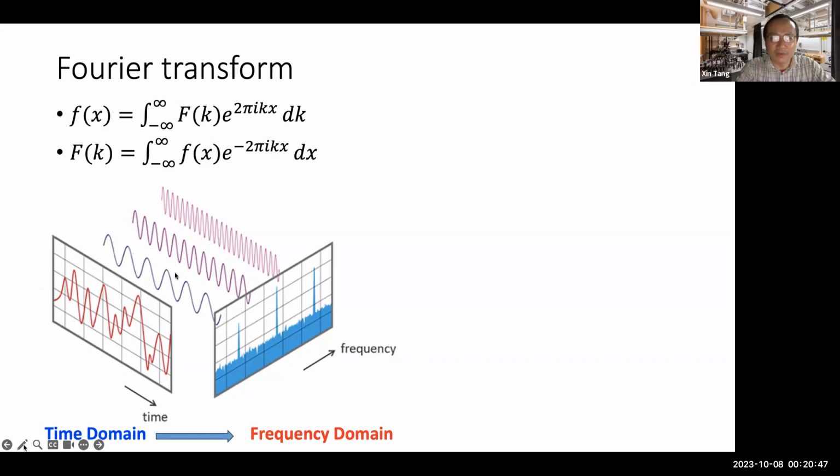And then because they have a different frequency, by doing this Fourier transform, you can convert this to a frequency domain, magnitude versus frequency. So it tells us this low frequency, and what's the magnitude. This peak indicates this curve. Another one here, higher frequency, indicates this one. Even higher indicates this one. Okay, so this curve is coming from the Fourier transform. It tells us the frequency information. With this frequency information, and also the magnitude, you can also convert it back to the time information.